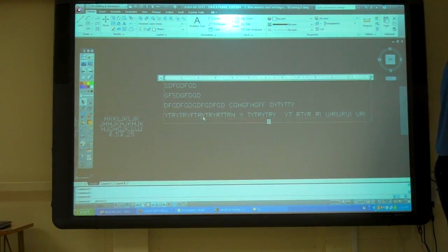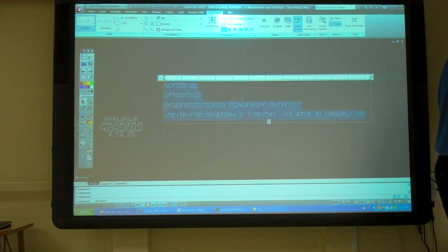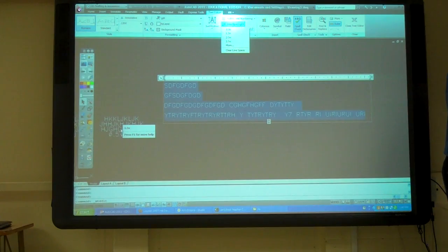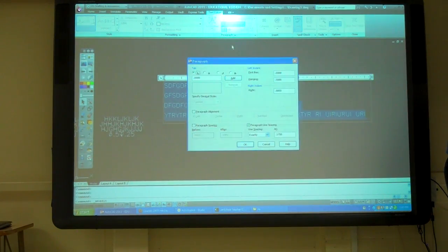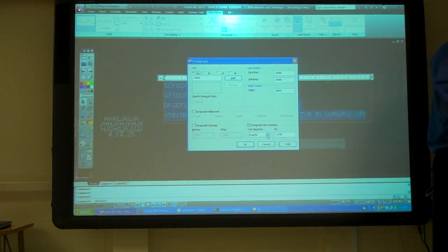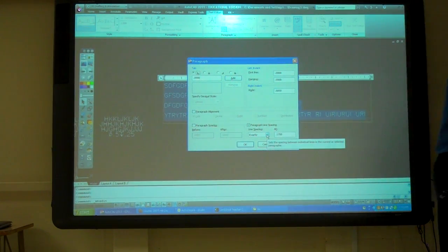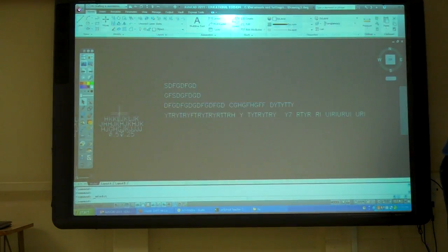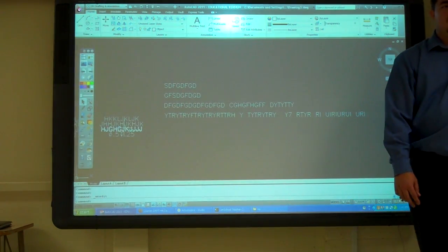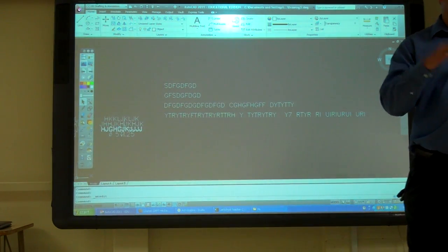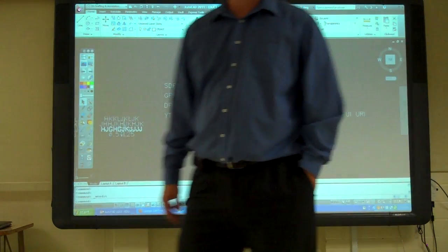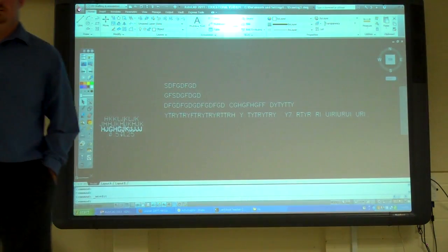Right, because over here, I moved them closer to 0.05. But I can't really see what I'm doing without hitting enter, going back and changing it. So I don't have the control that I did over here with DTEXT. But they're both there. You can use either one whenever you have to do text, which won't be too often.